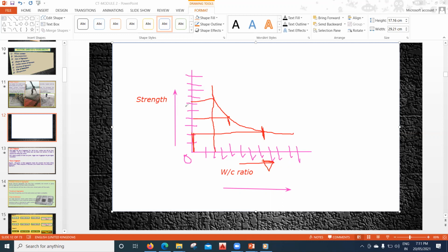So that is the reason whenever we do the concreting, we don't add external water, because if you add more and more water, then your water cement ratio is going to increase. If your water cement ratio increases, then what is going to happen? The strength is going to come down. So that is the reason I told you, whenever you add more water, make sure you add a corresponding amount of cement also, right? For example, I'll take another example for that.